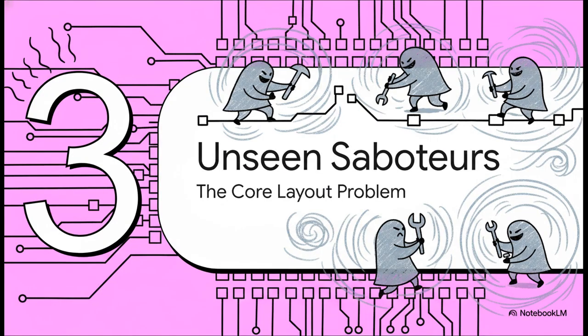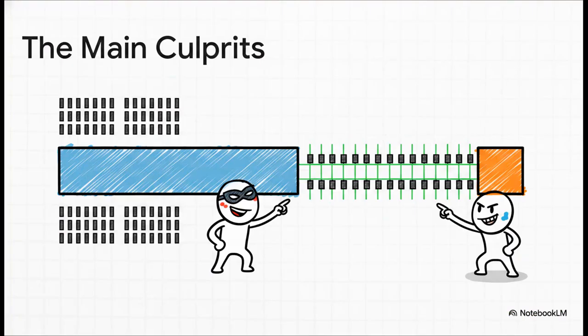And this is where we get to the heart of the problem. You have these engineers who have carefully designed this perfect amount of stress to make the PMOS devices fly, but it turns out there are these little saboteurs hiding in plain sight in the chip's layout, and they're messing everything up. So let's meet our two main suspects. They're called diffusion breaks and gate cuts. And you can't just get rid of them. They are absolutely essential. Think of diffusion breaks as tiny fences to keep different active parts of the chip from interfering with each other.